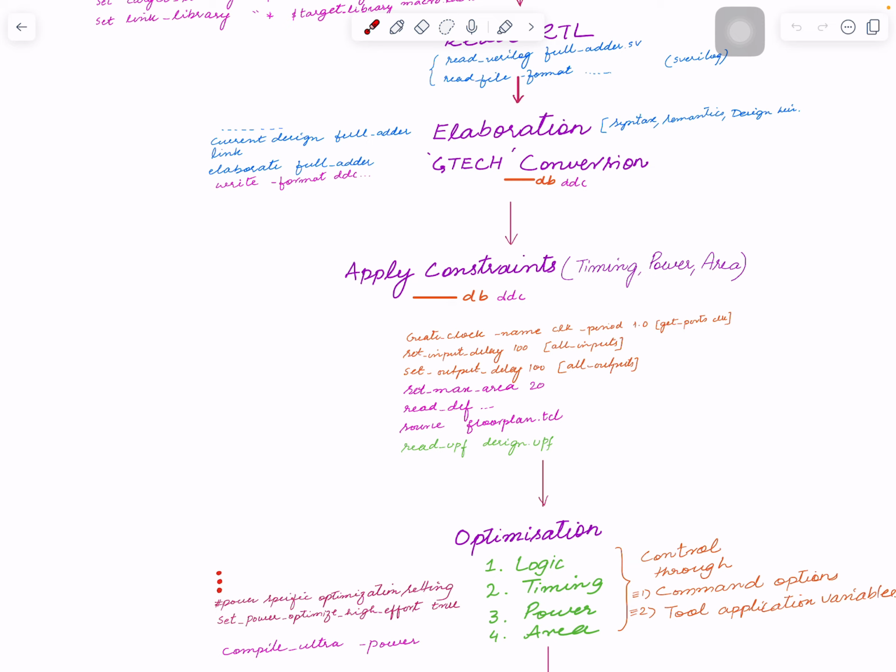You will see that, and maybe it's a separate topic, that gate level synthesis has become more of a physical aware gate level synthesis. And even at the time of gate level synthesis, the modern tool Design Compiler, or I should say Fusion Compiler, or similar tool from other vendors, they have the capability that even at synthesis level, tool can see your floor plan and different constraints with it. And when it generates an optimal netlist, it can optimize in such a way that given the dimension of the block, given the location of the pins and type of metal used, it can really optimize the design.